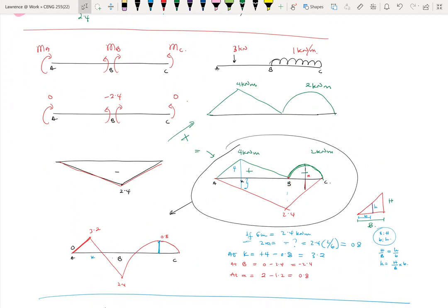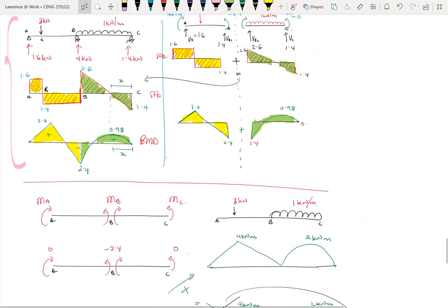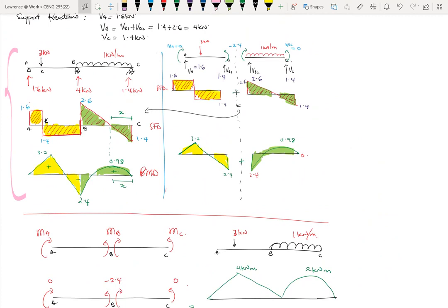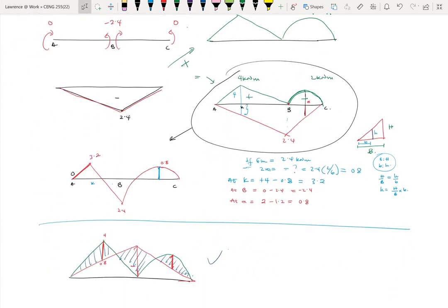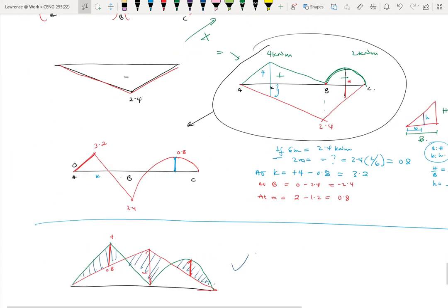So I also explained that there are different ways by which we can draw the bending moment diagram. I would prefer the first approach, but there's a way where you can superimpose the two moments and then draw the bending moment diagram. Usually when you superimpose, the values of your highest points are slightly different than if you draw them stepwise. Either way, it's fine. We are not looking for 100% accurate results because in engineering, there's always some bit of probability. Nothing is 100% certain.